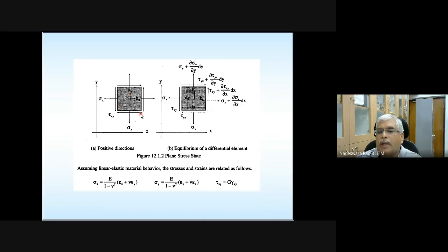And this is an element having dimensions dx along x direction, dy along y direction. On a differential element having dimensions dx, dy, what are the various stress components that are non-zero? For this case of in-plane loading, they are shown here. These are the stress components and these are the corresponding forces.